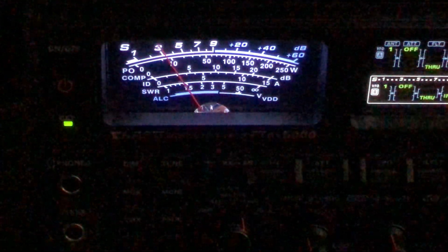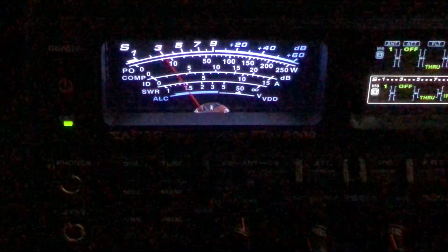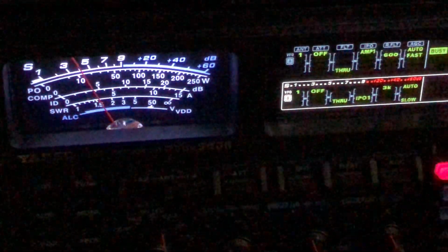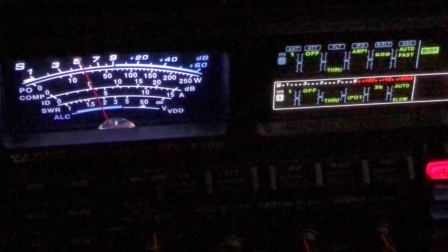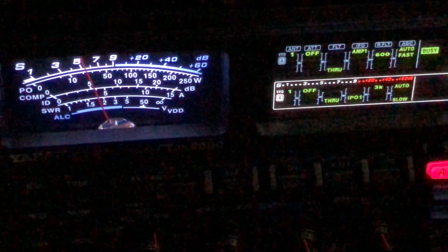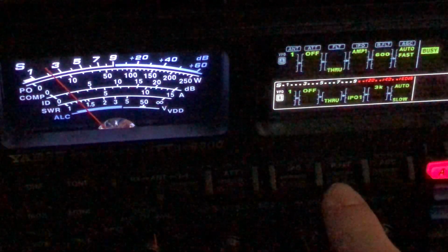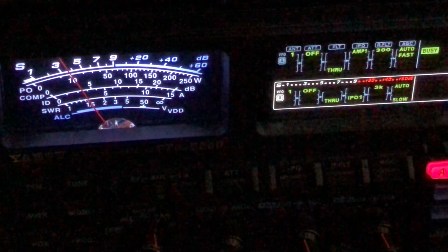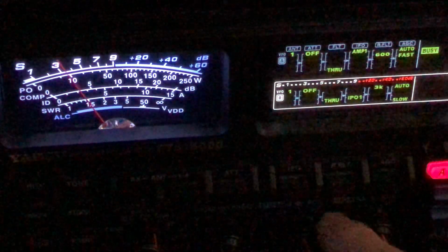I'm going to turn on digital noise reduction, which already helps. I'm going to pan a little bit over this area here so you can see that I'm on a 600 hertz crystal filter. I can, whoops, hit the VFO. I'm going to switch over to a 300 crystal filter. You see how that took a little more noise out compared to that?